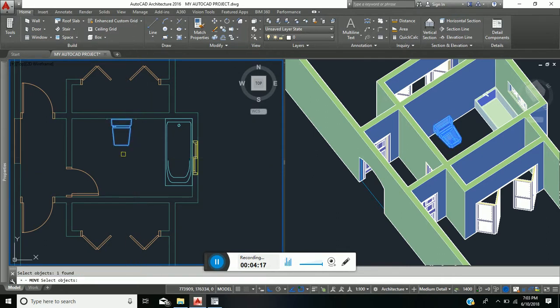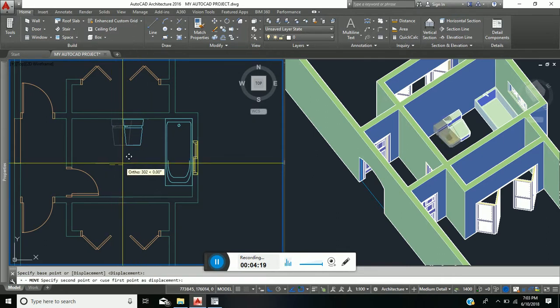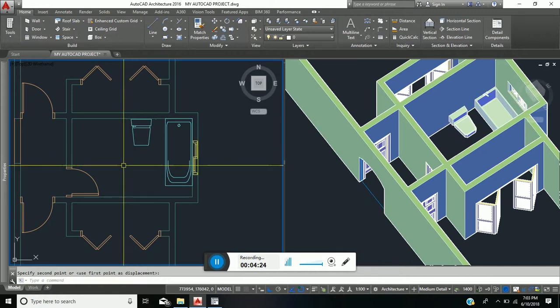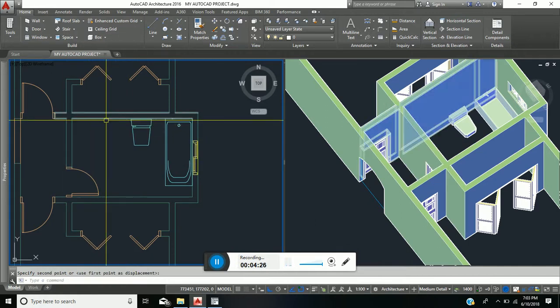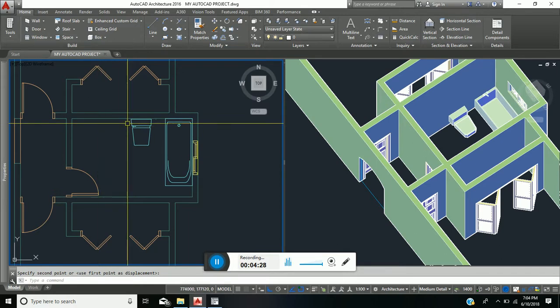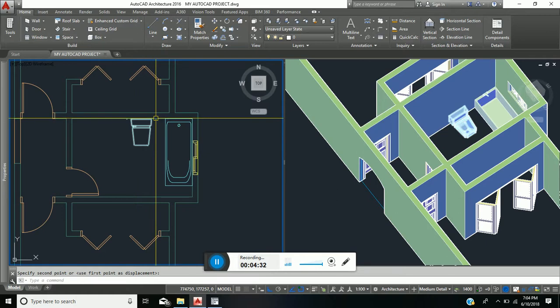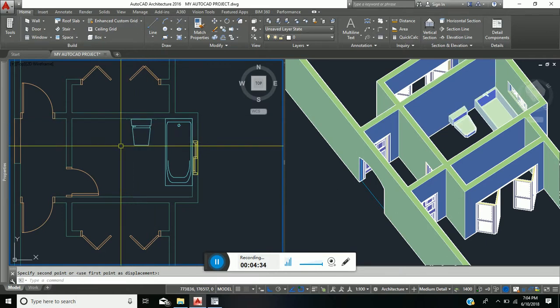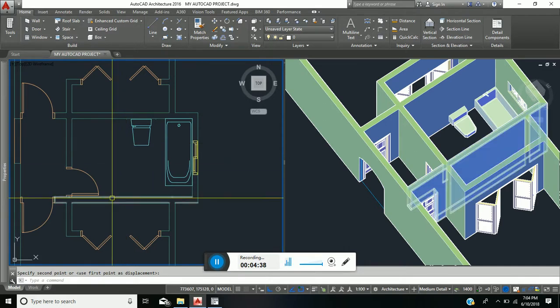And also I'm going to be moving it again a little closer to the bath, leaving enough space for at least a double sink. If you notice, the toilet comes with two dots to the left and the right, indicating that no other fixture should be placed within that area.